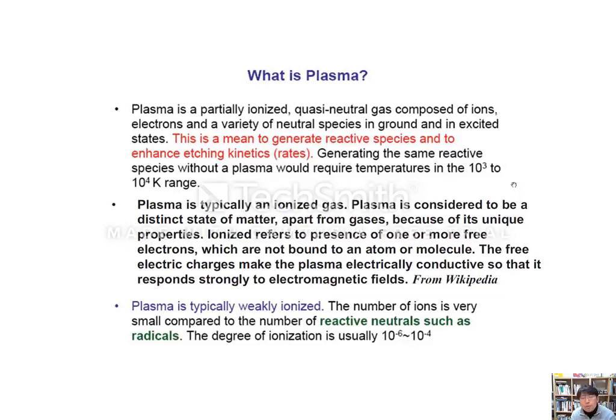You do not want to have a high temperature in your chamber because the high temperature process causes residual stress at the end. Let's say you deposit a certain material at very high temperature, and then to bring it down to room temperature, that deposited film should be cooled down to room temperature, right? Then what happens? There is a thermal stress induced during the temperature change. That causes either the deposited film to peel off or to have very high stress.